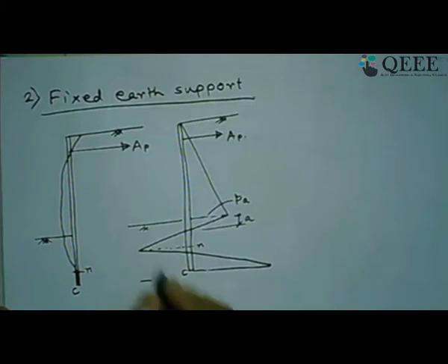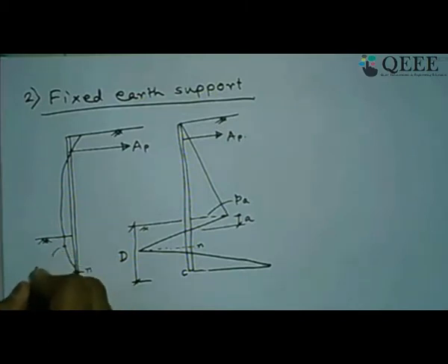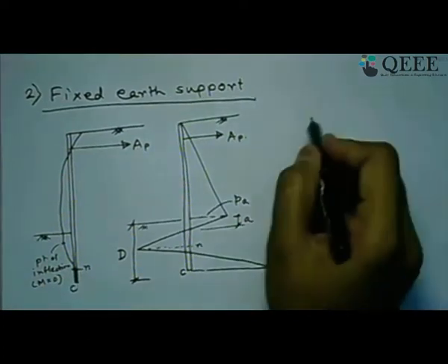Now this complete depth we are going to find out at the end, and this point is the point of inflection. Let us say this is the point of inflection. That means here moment is 0. That's what it means, as we know.